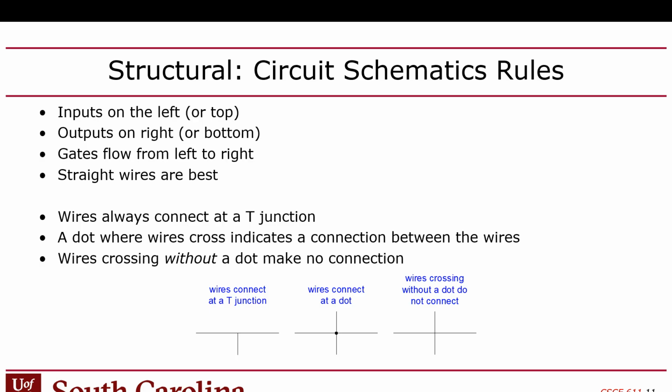So the T-junction is basically what's called a fan-out, where you have a wire coming here from the left, and it splits off into two directions, to go to two different inputs of two different modules. But when it splits off, instead of splitting like a fork, generally one of the paths will go horizontally and the other one will go vertically. Now it may be the case that the input is coming from the bottom and it splits to the left and right. That's possible too. But the point is if you have a T-junction, there's a short there, they're connected.